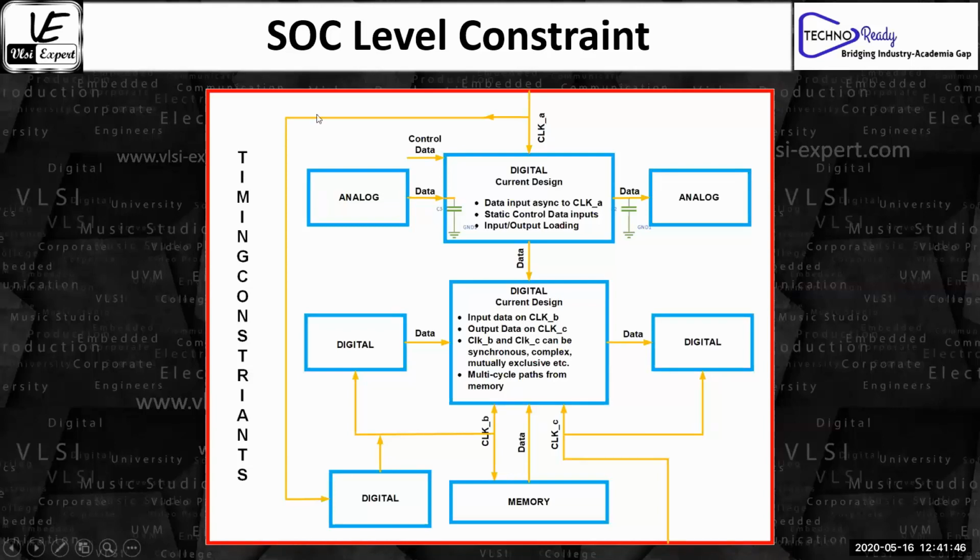I have a question. We'll consider all asynchronous paths as false paths in synchronous design, right? We'll fix that in CDC, I think. Yes, you're correct. We can define those clocks as a false path, right? We won't be able to capture the timing for asynchronous paths. We don't capture the timing for asynchronous paths. We usually try to maintain the loading and the transition for them.